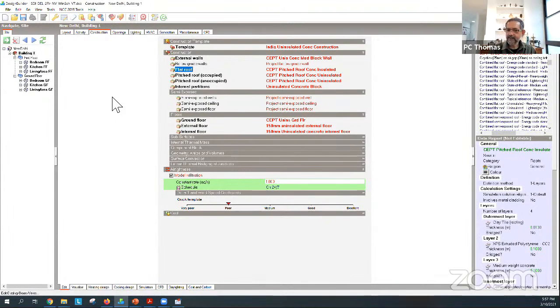And typically it's quite difficult to try to predict what the air leakage is. And usually we do that by doing a blower door test and testing out a bunch of houses or schools or whatever, and coming to some idea of how much the leakage is. And then depending on your construction, you try to make it tight by trying to reduce the gaps where the windows are fitted.